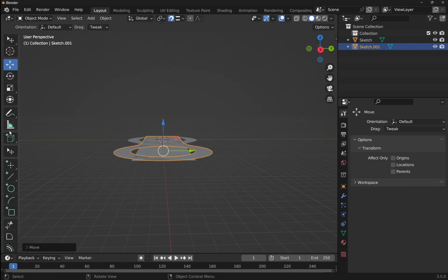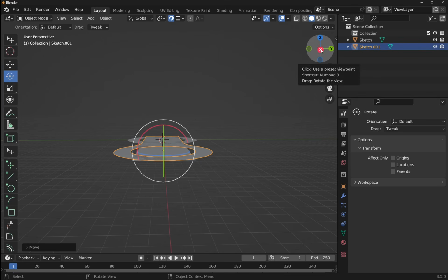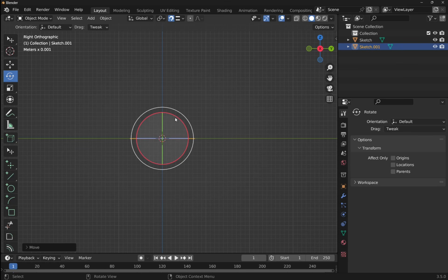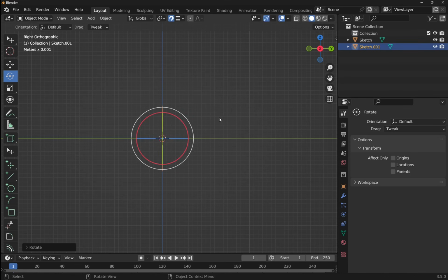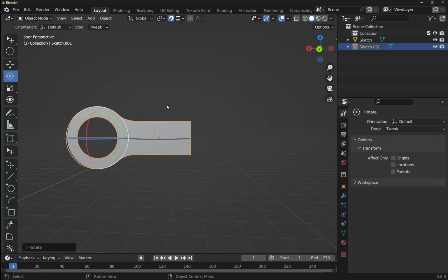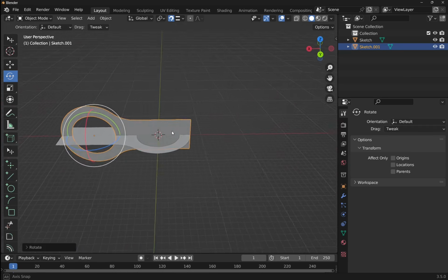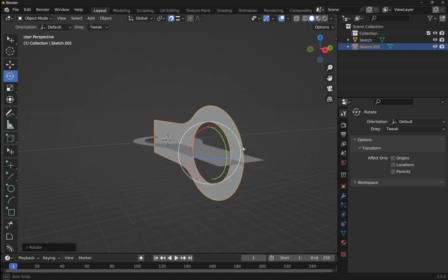And now I'm going to use the rotate tool. So I can come down, use the transform or just the rotate. Let's click on the X. So we've got that there. I'm going to highlight the X, bring this around and type in 90 degrees and release the mouse button. So we've got those there. And this is the way we will actually place these sketches in here.